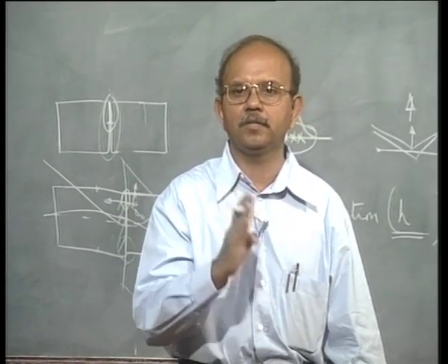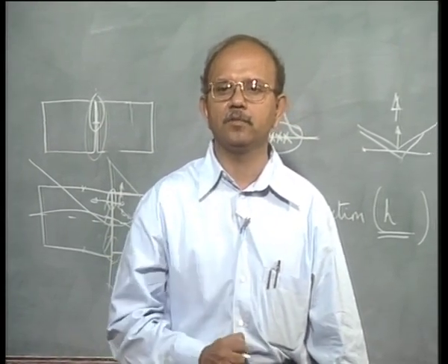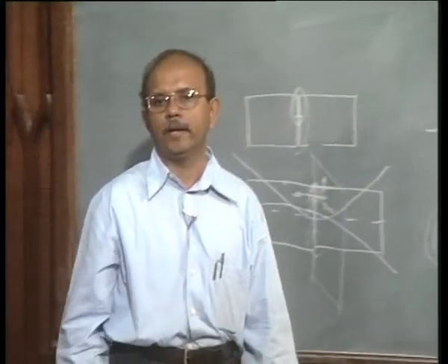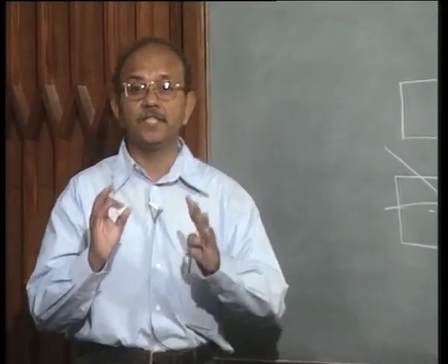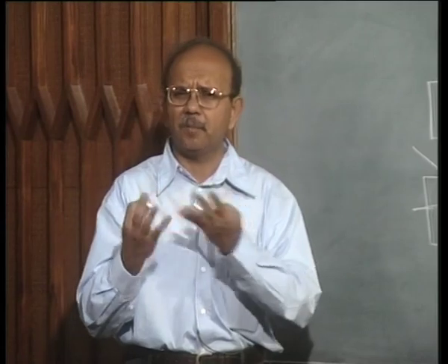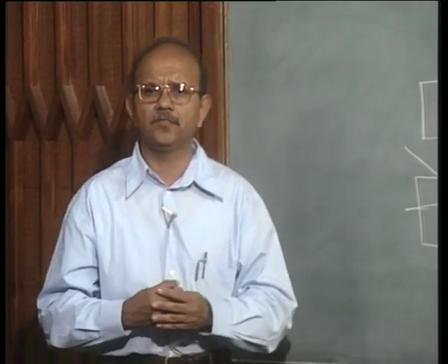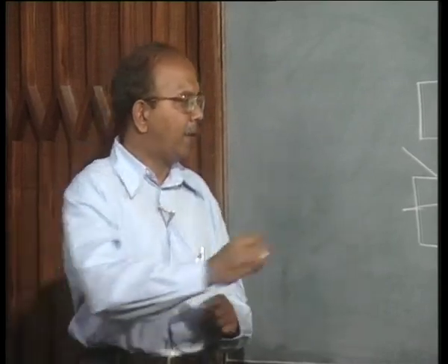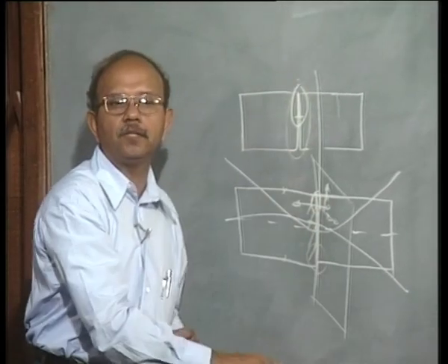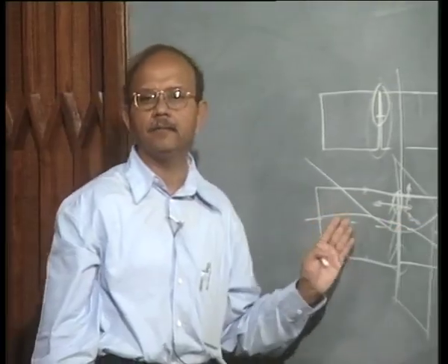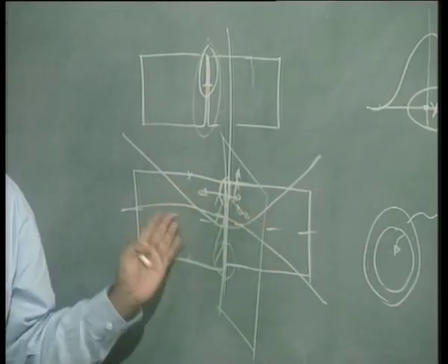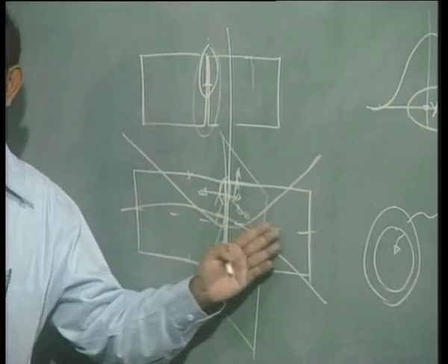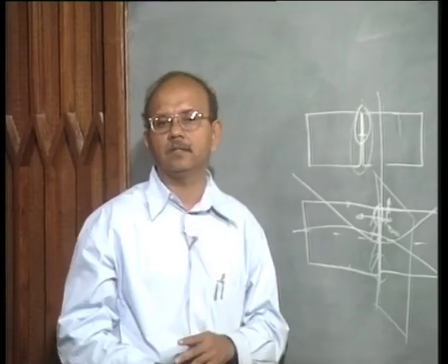What causes symmetry, or when do you apply symmetry? You apply symmetry when you are sure of the physical behavior of the structure. You should have some understanding, even a common sense understanding, that about the symmetry plane, on either side of the symmetry plane, the deformations would be symmetrical.